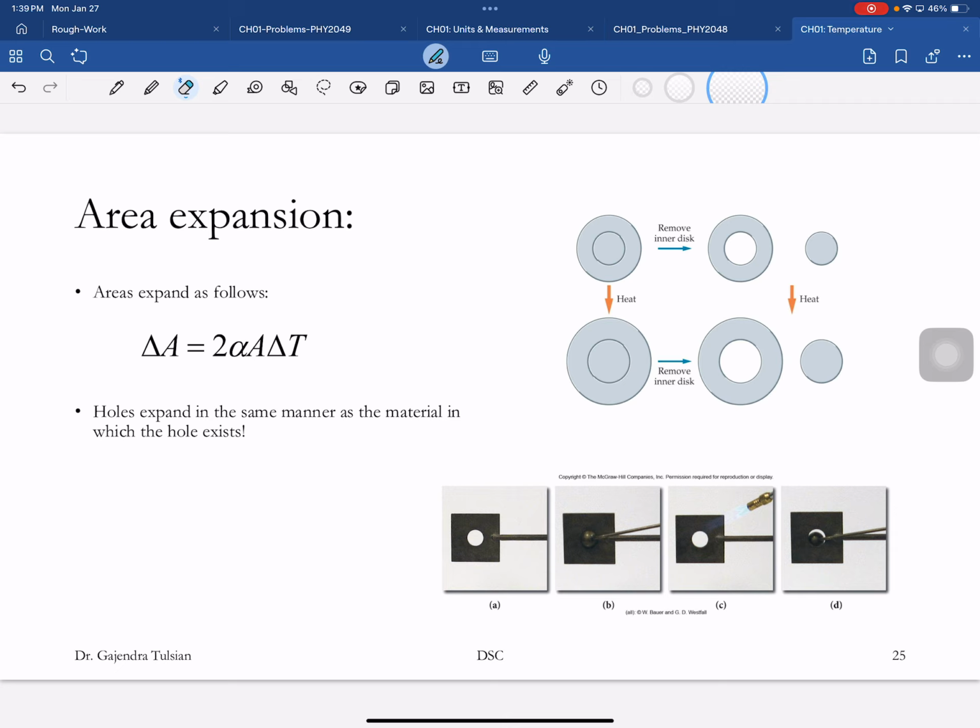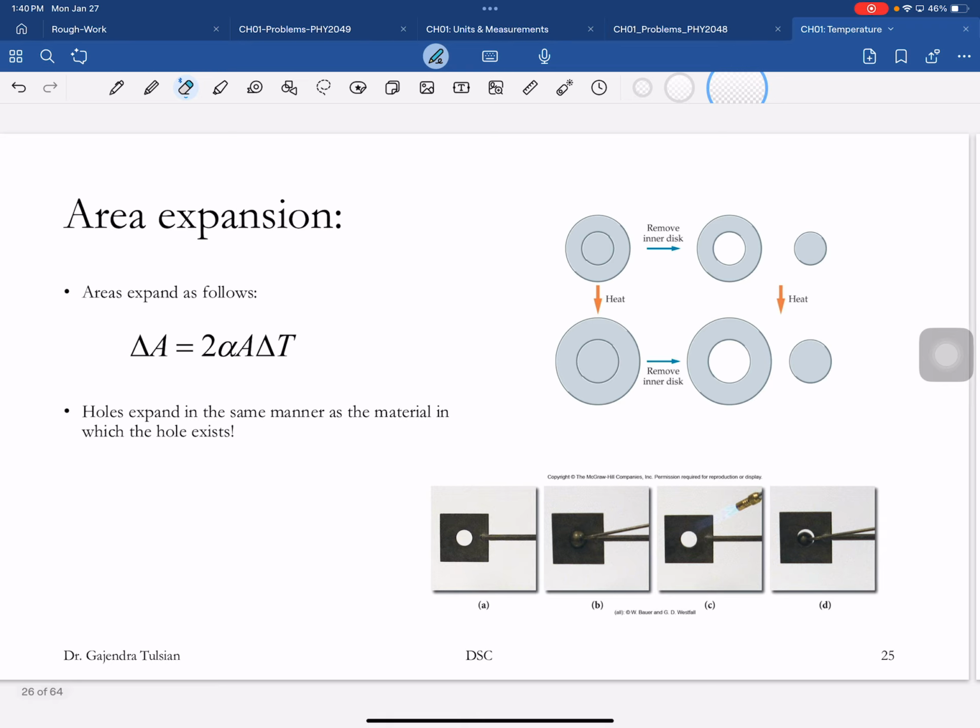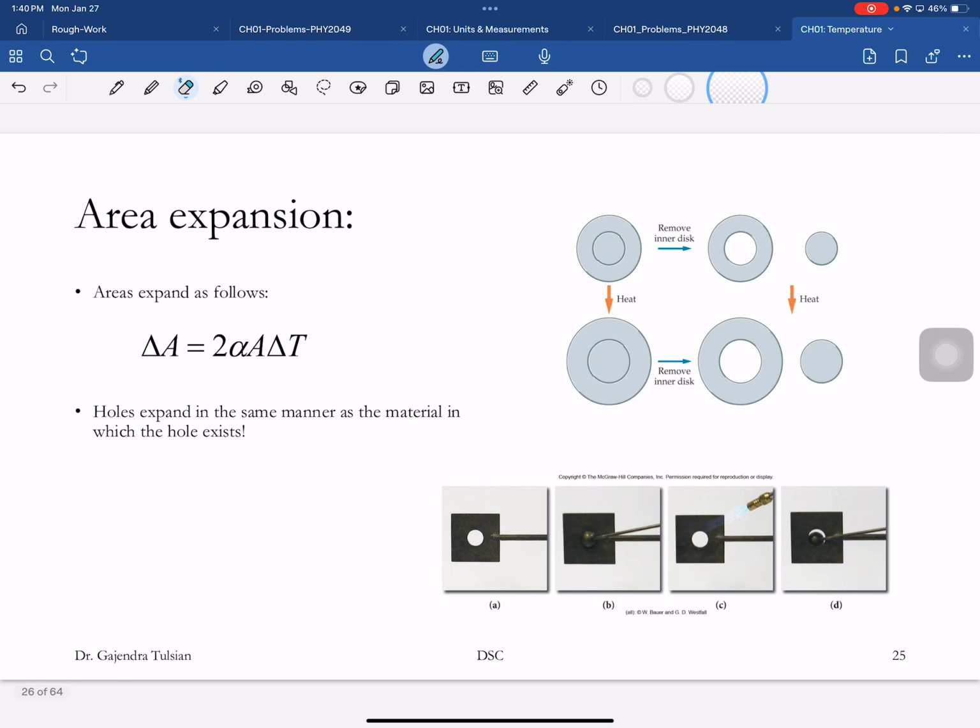Aluminum strips very easily. So how do you get around that? Cool the aluminum. You have these holes, and what you do is you cool the screws. You dip them in liquid nitrogen, and then you screw them in. And then when they warm up, there's a tight fit. So these kinds of tricks are used all the time.